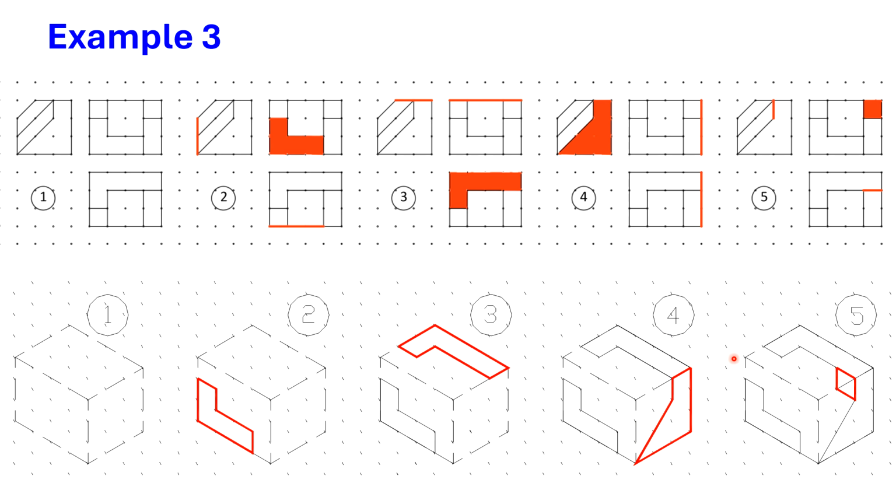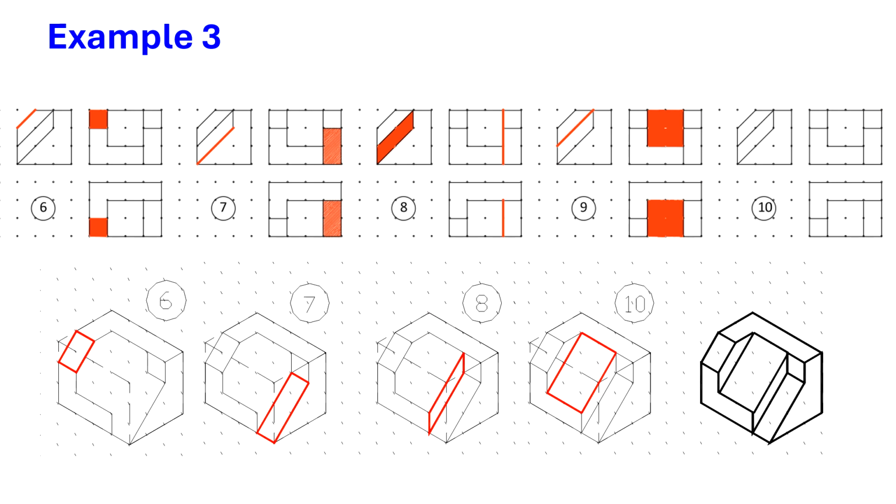Then let me go to the next surface. So I selected this surface. This surface in the side view is appearing here, and in the top view here. That means this is also a principal surface. So this is appearing in the front view, so it should be parallel to the front view. If you see from this window, it should appear. So we need to draw over here. So then 5 steps are over. Let us go to the next 5 steps.